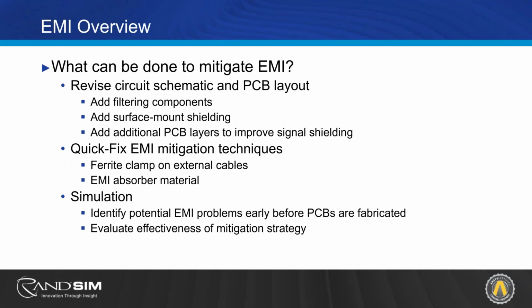Similarly, EMI absorber is another option that's quite expensive and is used often as a last resort when you're mitigating often cellular or any sort of radio desense issues. And so typically that's avoided for regular EMC compliance, but it's another quick fix, cost prohibitive option.